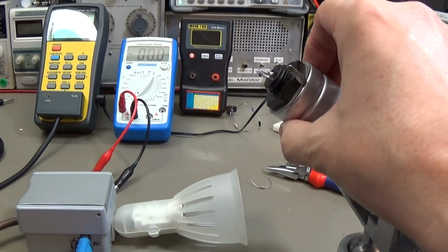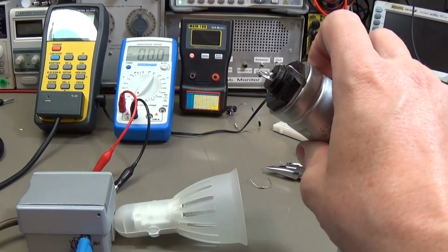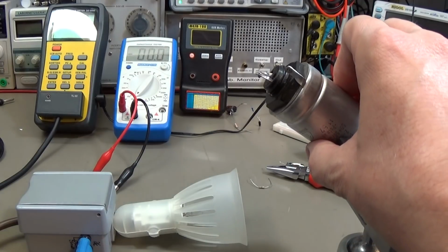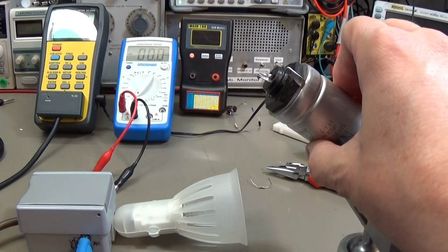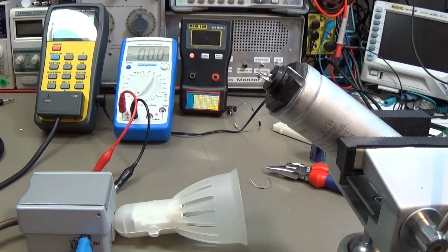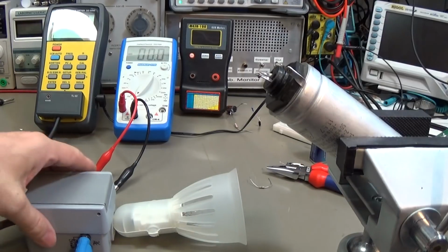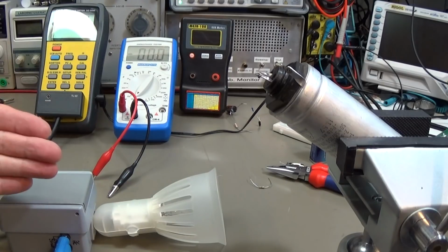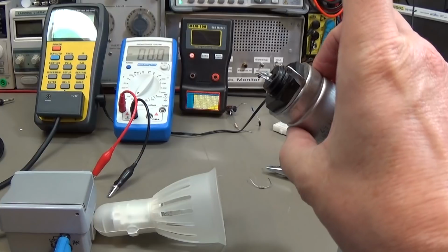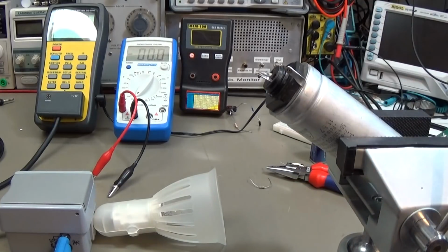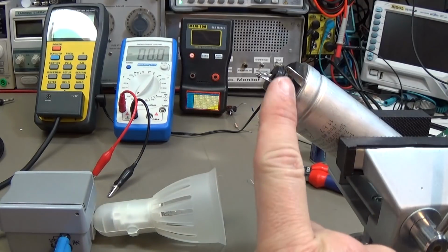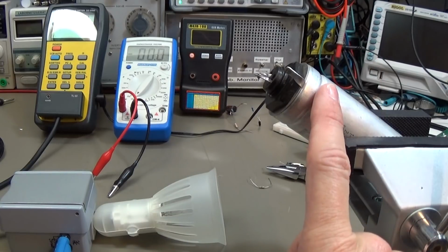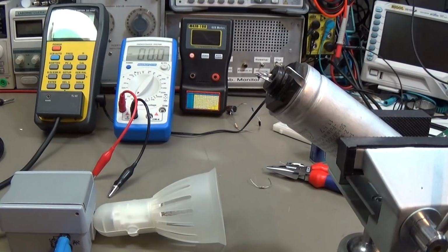our leakage current, and we know from our earlier videos that all electrolytic capacitors have a leakage current, so that is normal, but the leakage current should not exceed a given value, and that is what we want to test now. And we have our bulb in front once again to protect us if we really have a short with this capacitor, right? And therefore let us test if this capacitor is still in spec.